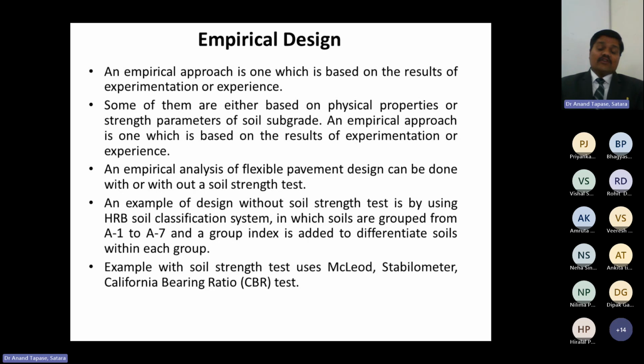If we look at that experience in our case, we do have various different geological conditions, the climatic factors are different, we have a terrain classification, the parent rock varies from state to state, from province to province. So how can we rely on such experiences that those people have observed in their continents? This is the empirical approach that we have followed while designing the pavement. There are examples of design without soil, whereas there should be soil conditions and a soil test should be done. They observed something in their continents and they are following it blindly.